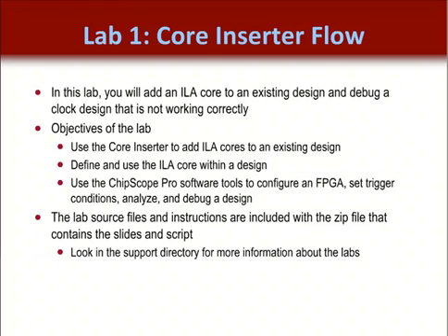This lab shows ChipScope in its simplest form and shows how easy it is to set up designs, analyze, and debug. The files and lab instructions are in the zip file you can download with these slides and script. Note that a Spartan 3 demo board is used in the lab, but if you have the finished pinout of your demo board, you should be able to use your demo board with this same design. All you'll need to do is modify the design's UCF or user constraints file to match the demo board you're using.